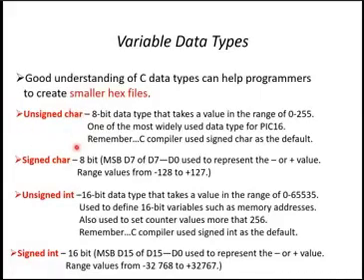And because the size is 255, we need to assign half of it as negative and the remaining half as positive. So that's why it is negative 128 to positive 127. But this is actually similar 8-bit data. So if your data is 200, you can declare it as unsigned char. But if the value is negative, let's say -1, you need to assign it as signed char. Why we need to properly assign, I will explain later.